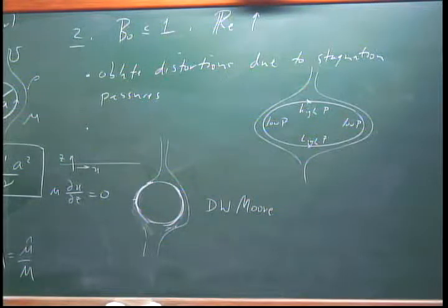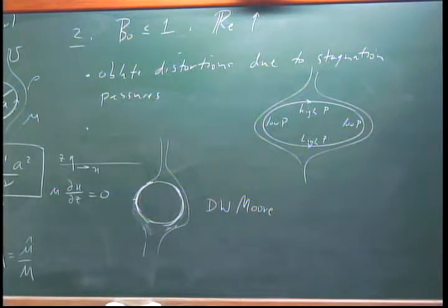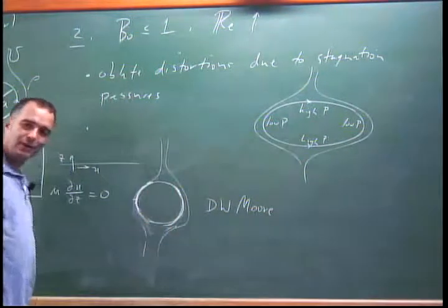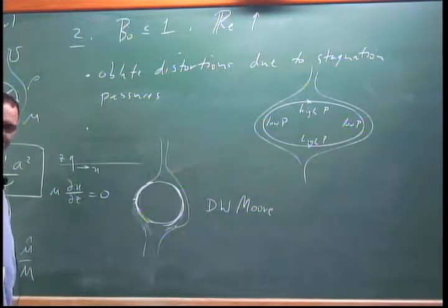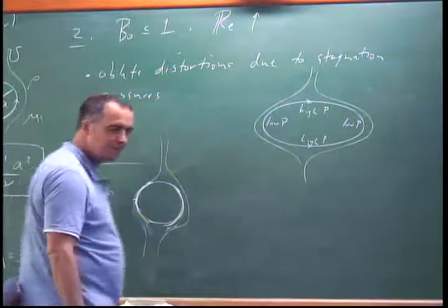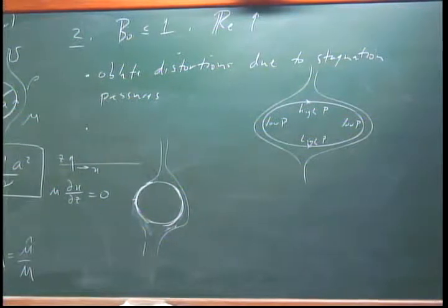So potential flow past the sphere is wrong for flow past bubbles. It's also wrong for flow past rigid surfaces. It's a different type of boundary layer, but you still need a viscous boundary layer. You okay with that? It's interesting because it's kind of subtle. It's in contradiction with what we do with, say, Kelvin-Helmholtz instability, where you have a shear, a jump of velocity across the interface.